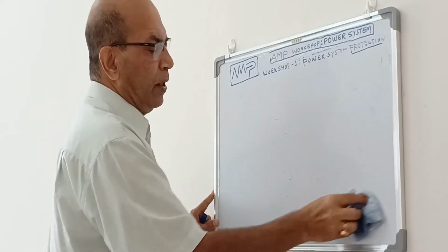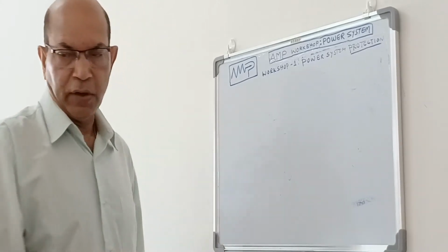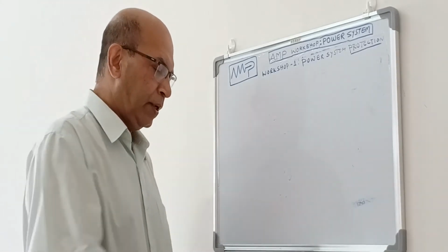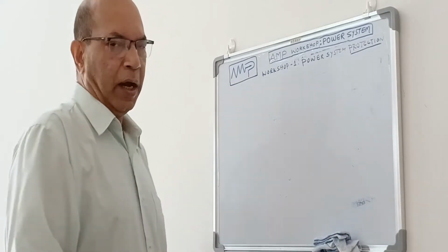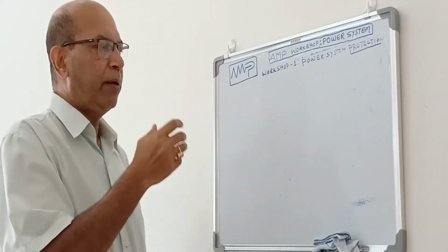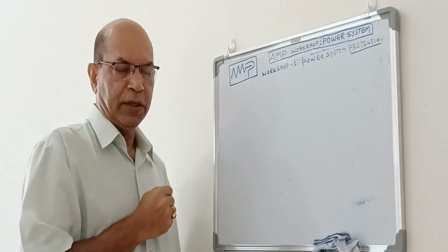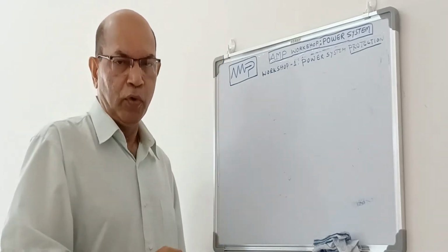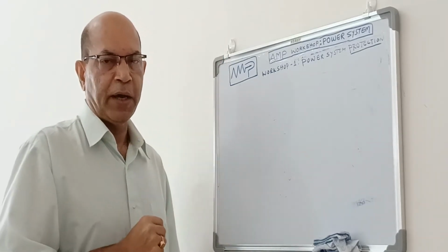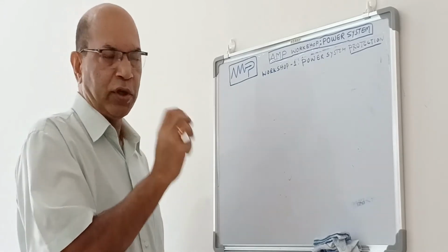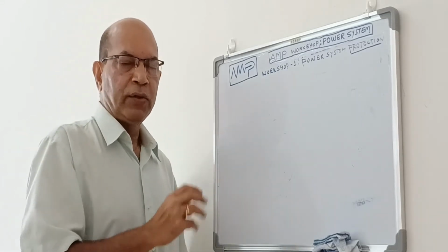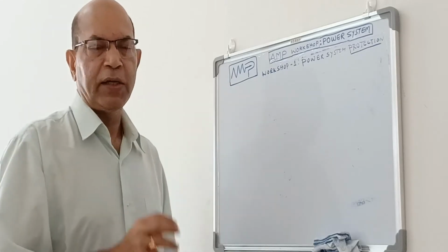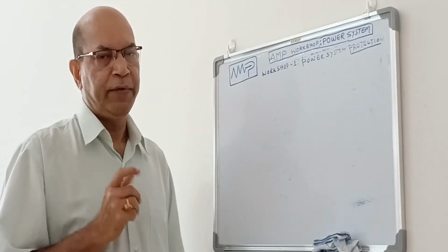Until the current is there, it will be magnetized, meaning that the solenoid will act as a permanent magnet. And if near that magnetized solenoid there is a plunger or an armature, a magnetic material, it can pull or push depending on the direction of the magnetic field. That push and pull, which I showed in the coil relay, can be used for the same purpose. That is called an electromagnetic attraction type relay.